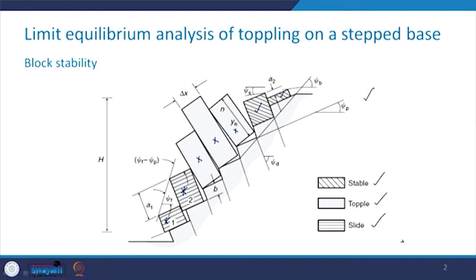And it was assumed that the moment the block at the toe slides, the slope is considered to be unstable. This distance, which has been shown here by B, is constant for all the blocks. These were the assumptions involved. And if you recall, we obtained the number of blocks that will be present in such a type of rock slope, and that we represented as n.